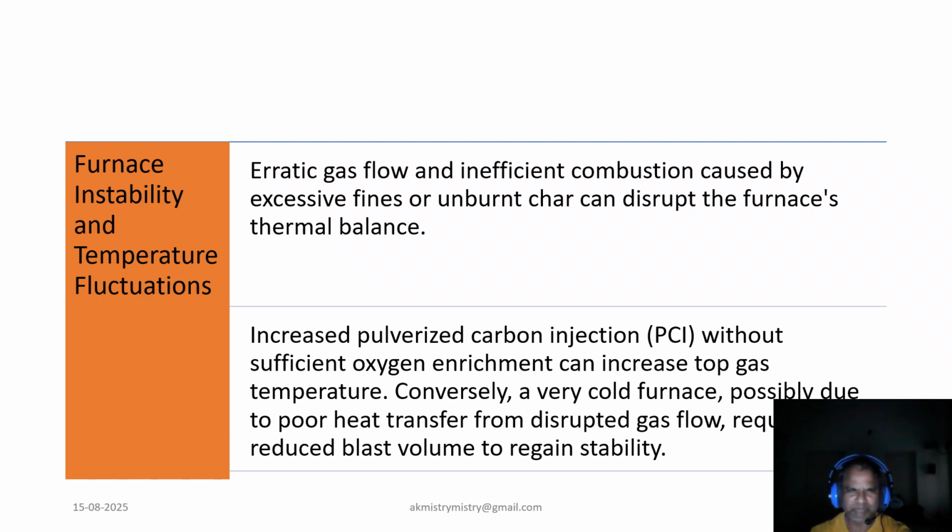Now coming to the unburned char and the fines disruption, where we can say that high PCI without oxygen management raises the top gas temperature. A coal furnace, often due to poor heat transfer, may require reduced blast volume to stabilize the furnace operation.